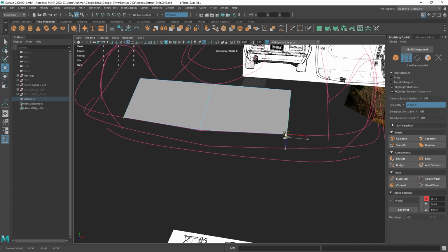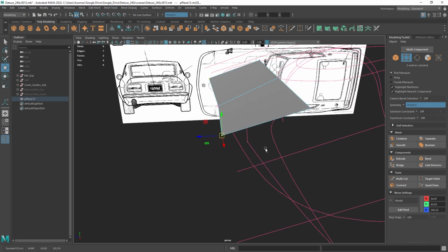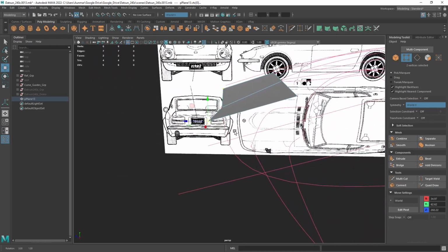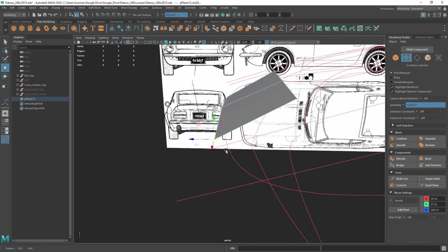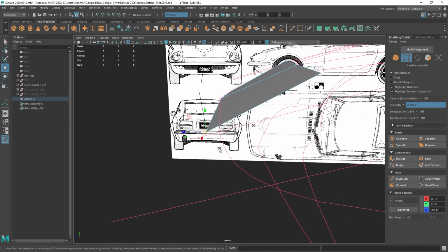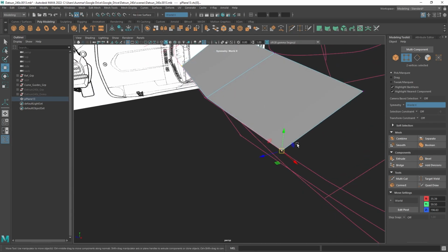All right, and the one thing that I use all the time that you're going to see is that if you have these vertices off in position, I like to use Control middle mouse to move off in the normal direction, so you can see what's happening there. So Control middle mouse moves in the normal, right? And then if I hold Control Shift, that does an edge slide. So you can see the word slide popping up there, right?